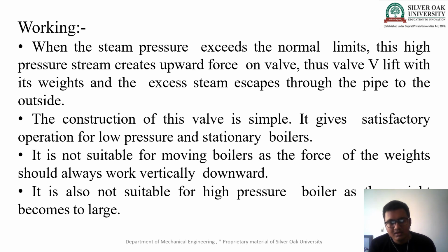When the downward and upward forces are equal, during working pressure the valve will not lift. But if the pressure increases beyond the working pressure, the valve is lifted and the excess steam escapes from the pipe to the atmosphere outside.